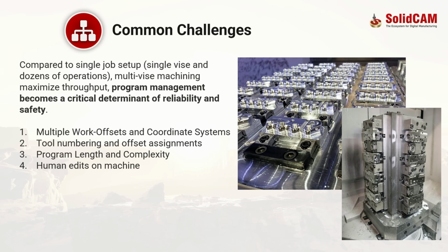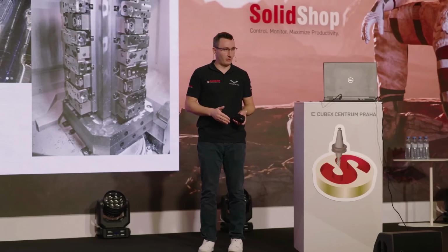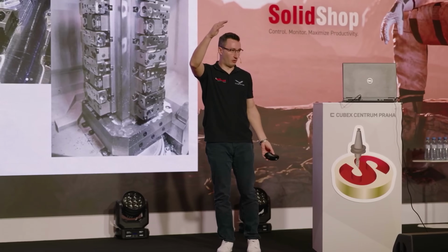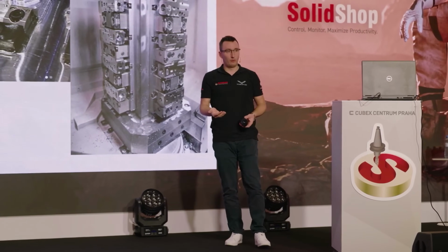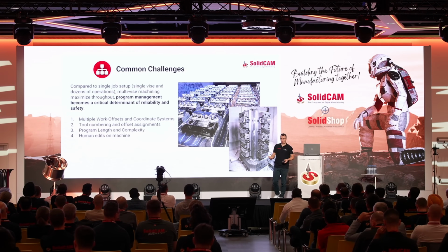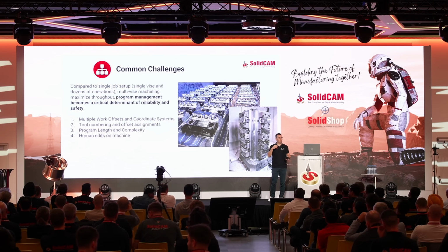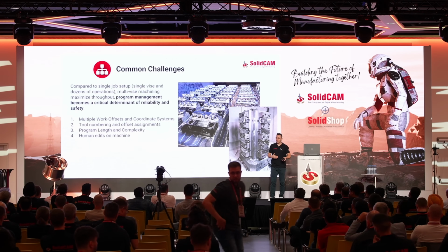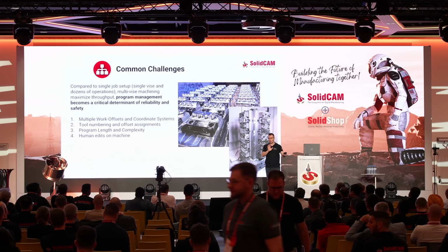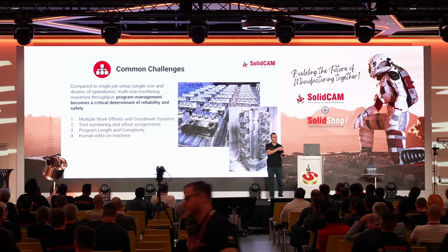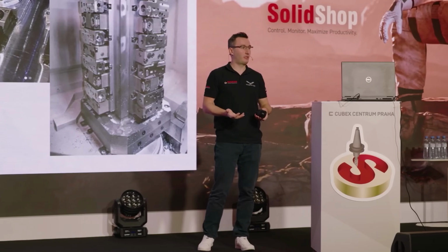Now, what is the different league? The different league is in the program length and complexity of these programs. The programs are much longer, okay? Now, the problem starts with the operator. I always speak with these customers about what you do in order to optimize the tool change. Because only by optimizing the tool change, you can save a lot of time. And not only that, another level is that you can analyze the angle of machining, and you can maybe machine multiple parts with the same angle without changing the tool. So there are tons of optimization that you can do.